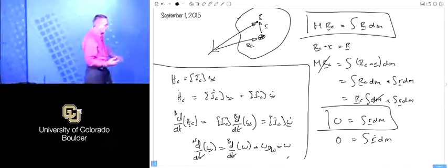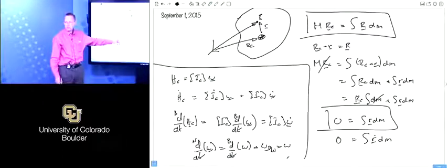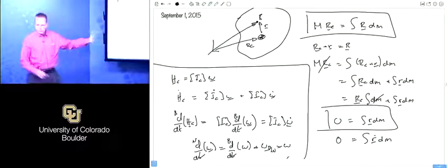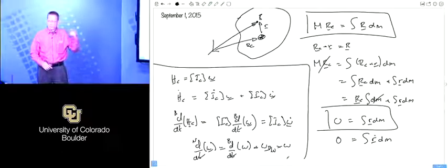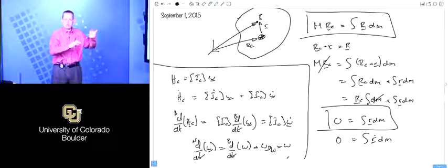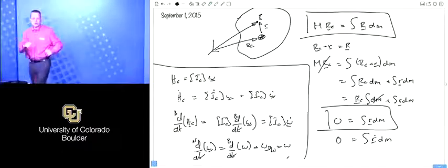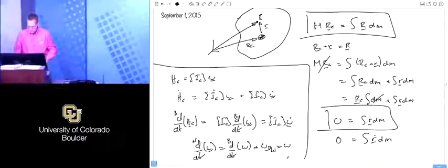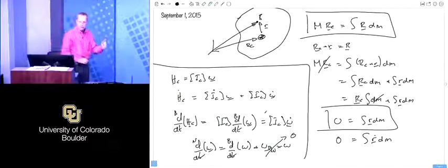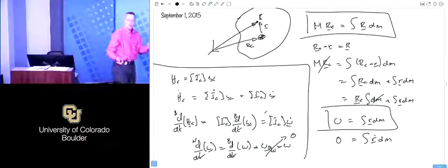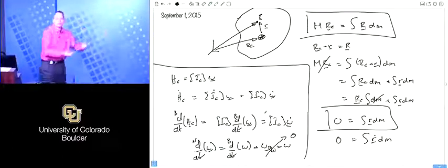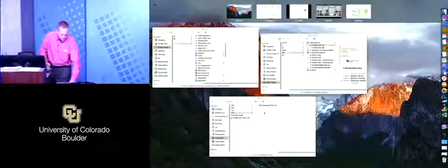Right. So omega here, if you just write this, is typically shorthand for omega B relative to N. It just gets a little tedious to write it out all the time. If you're doing control, especially a tracking problem where you have omega B relative to N, omega R relative to N, and omega B relative to R, I would recommend actually just writing it out. It's easier to keep track of until you really feel comfortable with that. But not exactly. So this term here is just going to drop out. So that's why. For the angular velocities of Q relative to R, the Q frame derivative and the R frame derivative will always be the same. That's what we're using here. So that's a nice thing to remember.